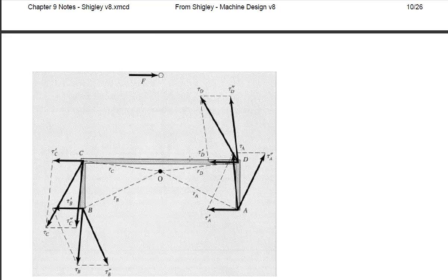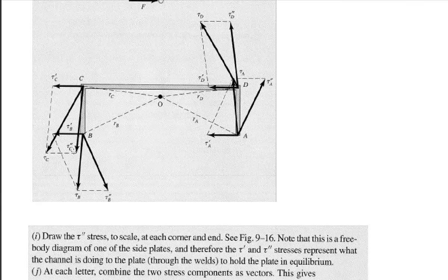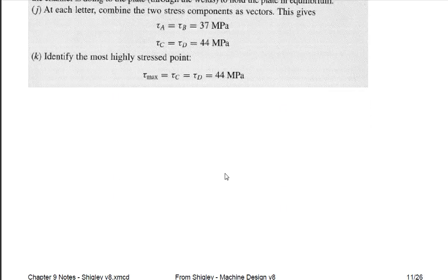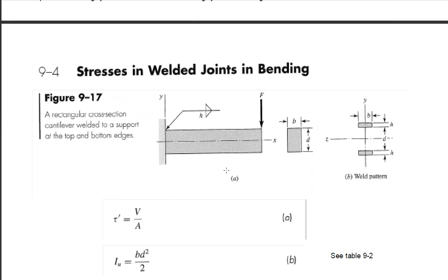And now all we have to do is a vector combination of the stresses. The author doesn't offer any assistance on that other than just do it. The vector flip-flop method that we used with bolts will work just fine here. You use whatever method you like. Okay, and from that we can calculate the shear stress in the weld.